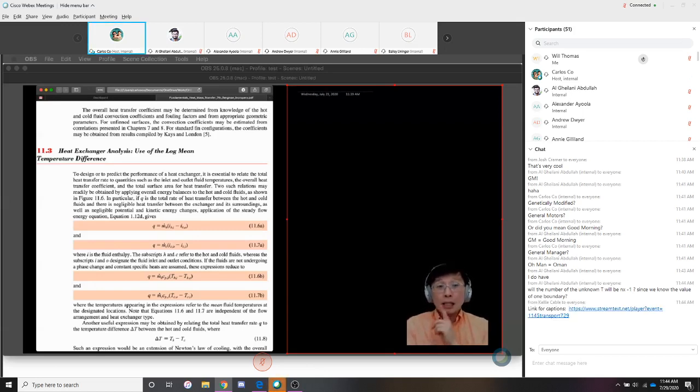So what happens is in the past, the number of unknowns was nx minus 2 because you know the temperatures at both ends. This time around, you also don't know the temperature at the insulated end. So you have nx minus 1 because you only know the temperature at one end. The other end, you need to solve for, right? But along with that unknown comes another equation, and that extra equation is the equation that you need for that insulated end.